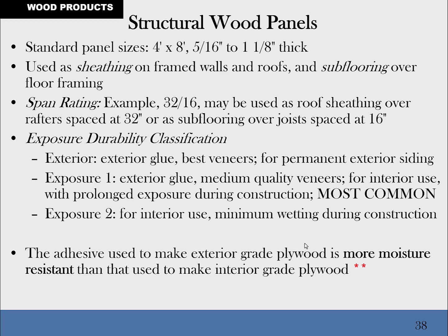And by the way, the bugs tend to like the glue better anyway because it's animal-based, whereas the exposure one and the exterior glue rating up top here are both using glues that are not made from animal parts in any way, shape, or form. They'll use a urea formaldehyde-based glue sort of thing.